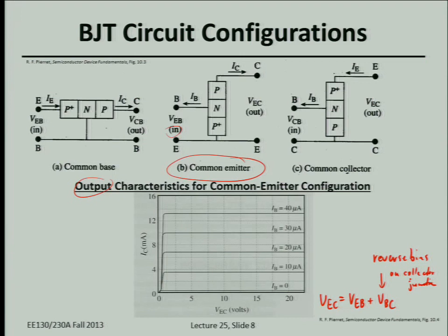Okay, so let's go back to the IV curve for a PN junction. How does the reverse bias current depend on the reverse bias voltage, ideally? It doesn't, right? And that's exactly why this current is flat. Because for each curve, IB is fixed.